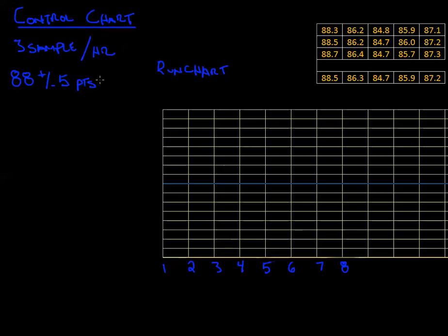This is the customer's specification, and the scale is called HRB. If you're familiar with hot rolled bar or heat treating processes like normalizing, spheroidized annealing, things like that, you'll be familiar with this scale, HRB. It's for moderately hard steels. So HRB is just a scale, and here's the specification, 88 plus or minus 5 points on this scale, and there's specialized equipment for taking those measurements.